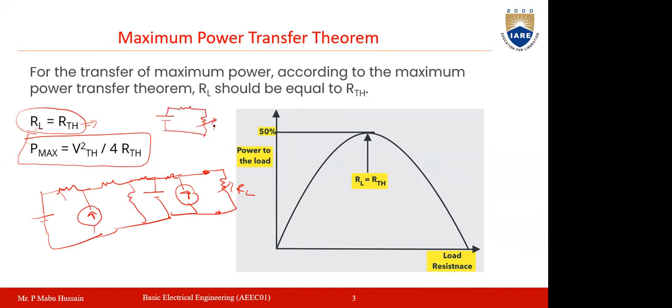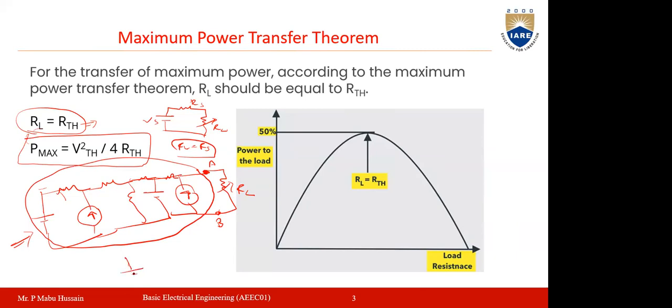For this, you can usually apply the maximum power transfer theorem, such that RL will be equal to RS. But if a complicated circuit like this is given, then first of all, between the terminals A and B, which are the load terminals, you need to find the equivalent Thevenin circuit. Then that total circuit will become V Thevenin in series with R Thevenin.